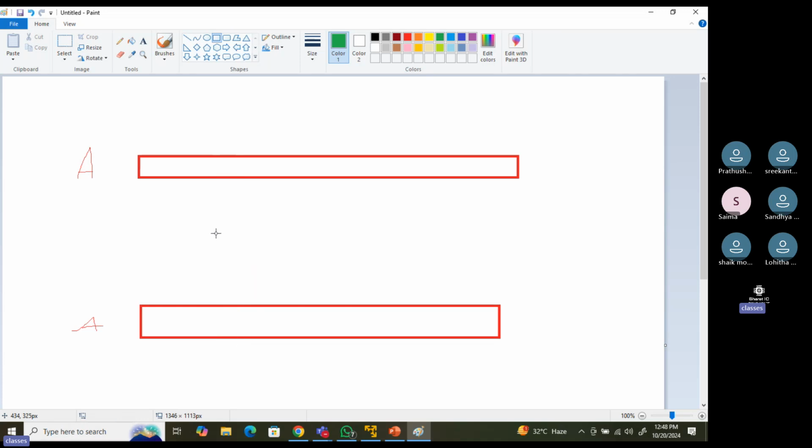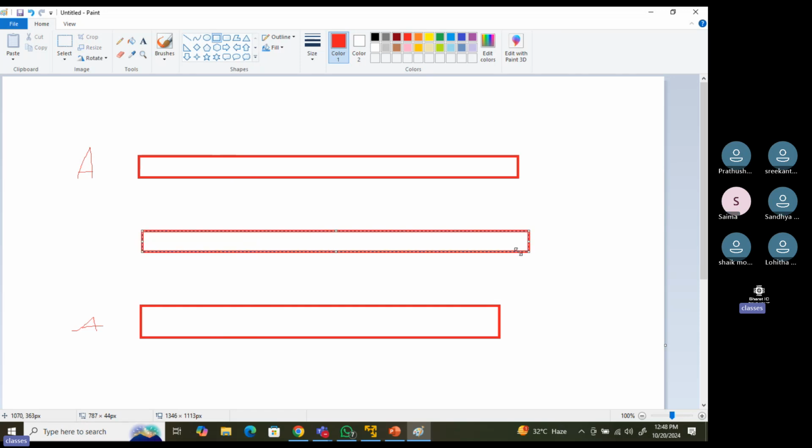But the problem here is another net is passing through this area, an M2 net, which is signal B. And some connection is there with an M3 connection here. An M3 connection has already been here, going to some other net. Don't consider this net, the other net. Now, if I want to draw an M3 on this one, it will overlap and get shorted. I don't have any space on the left or right.